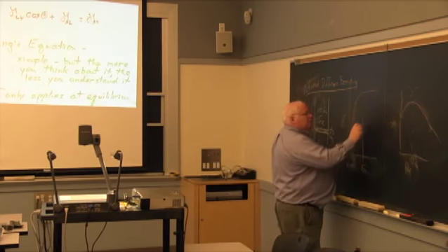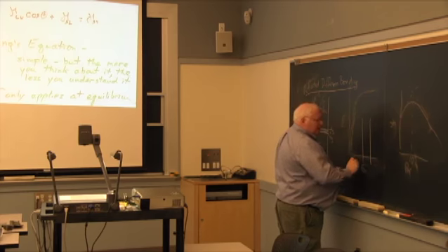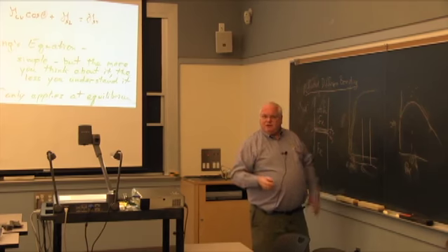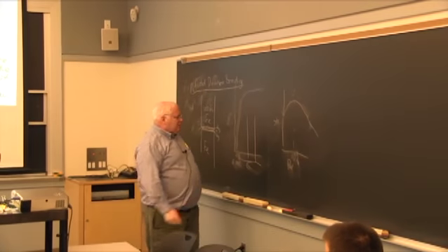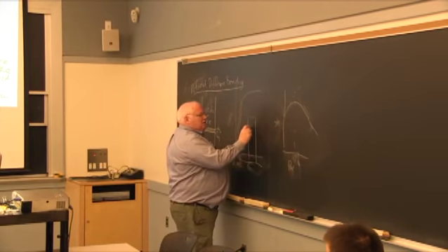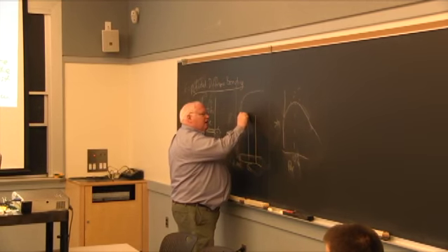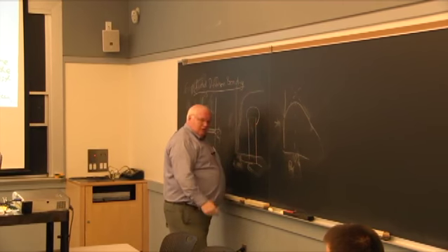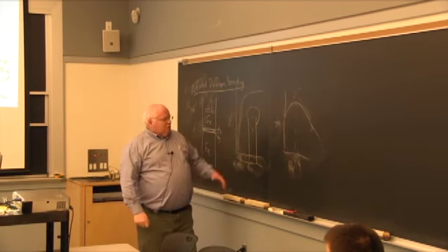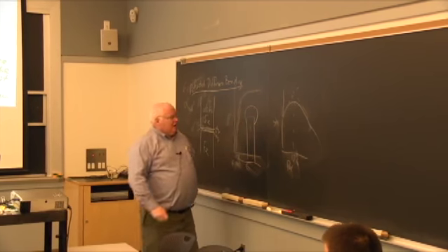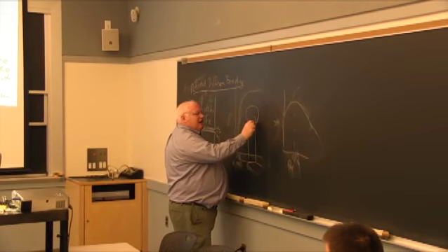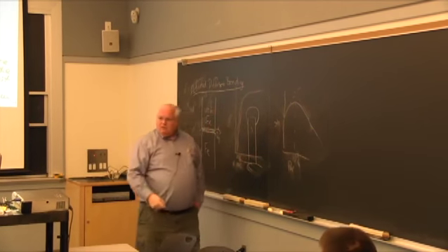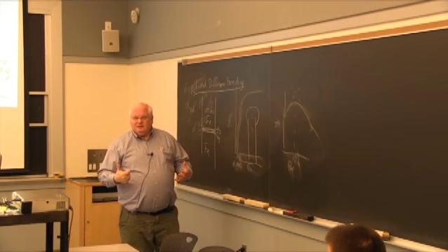But anyway, so Professor Sonnen called me up and said, well, Tom, I'm getting all confused. And I thought, okay, here's one of the better theoreticians in the mechanical engineering department. He's asking me a question. Anyway, so he was thinking of a solid that had a liquid drop on it. And he said, what's the contact angle? Well, I said, you just use Young's equation. Well, no, you don't. It turns out the contact angle here is not a function of the surface tensions. It's a function of the mass of this drop and the weight of the drop and everything else.